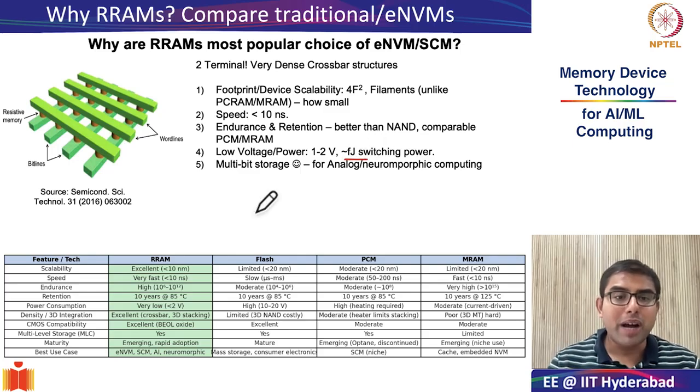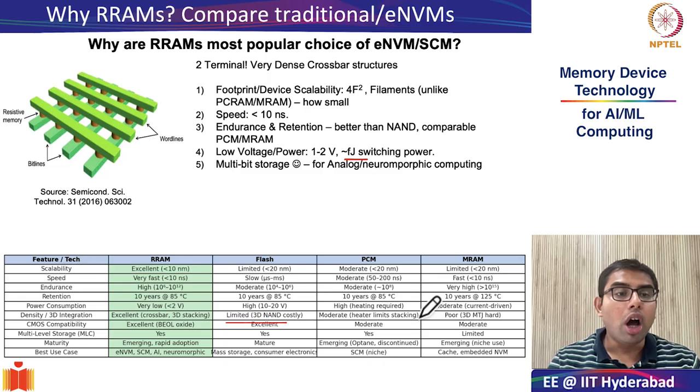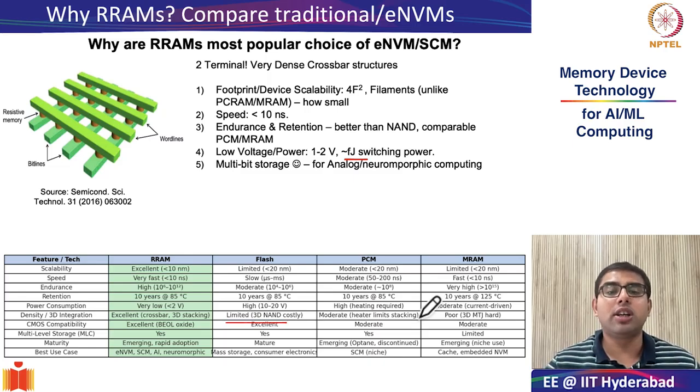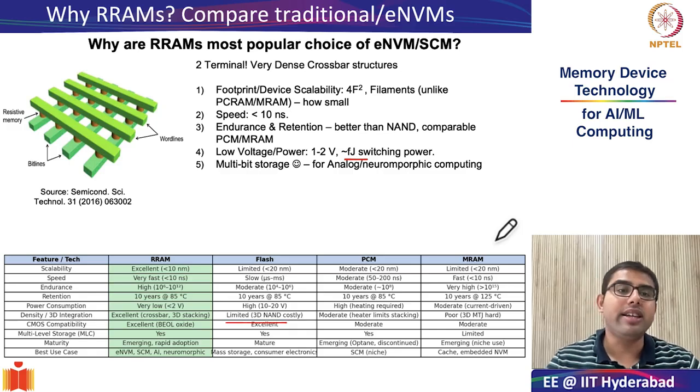Now, this is much better than your flash memory, and it is also much better than your PC RAMs. In PC RAMs, your reset process, which requires a lot of current, is what limits switching power, but definitely what is theoretically possible in MRAMs at least is better than femtojoules, but that has not been practically realized yet.